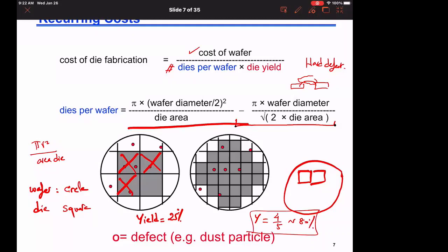That's why when we build a design, we try to target having the design as compact as possible, not only because I can fit more chips on the wafer and therefore I can make more money because I can fabricate things faster, but also because I can guarantee that my yield is much higher. Okay, so that is one important design requirement that we have to keep in mind, and that drives lots of design effort. Does anybody have any questions on this slide?